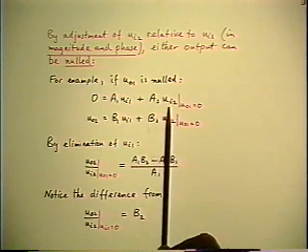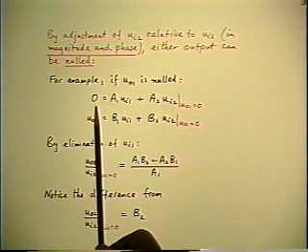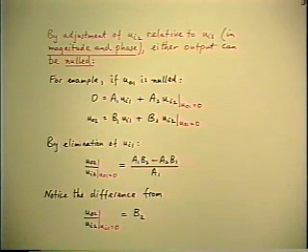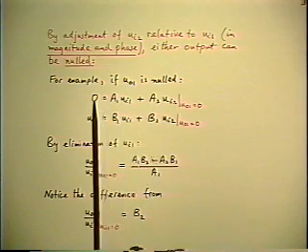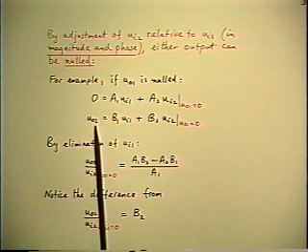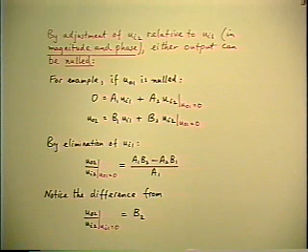Now, while you're doing this, looking at meter number 1, making it go to 0, meter number 2 is also wandering around, of course, while you're making the adjustment. But as soon as you stop adjusting, settled on the condition that makes output number 1 go to 0, meter number 2 now stops wandering around. And it stops at a reading which in general is non-zero.